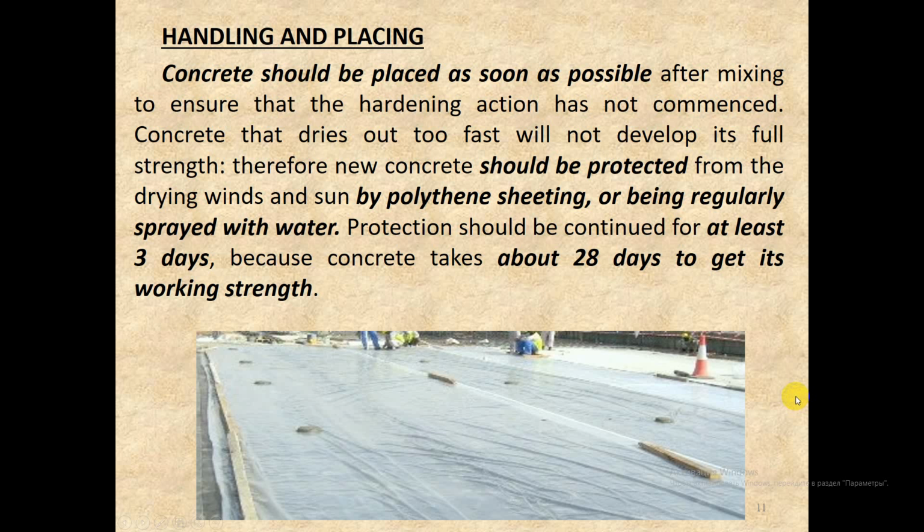Handling and placing. Concrete should be placed as soon as possible after mixing to ensure that the hardening action has not commenced. Concrete that dries out too fast will not develop its full strength.